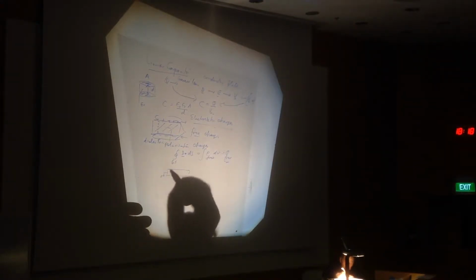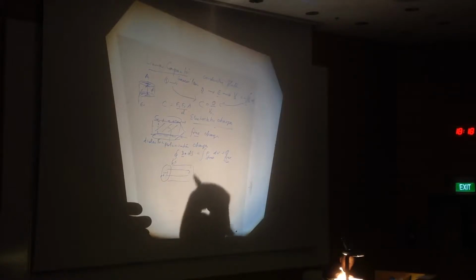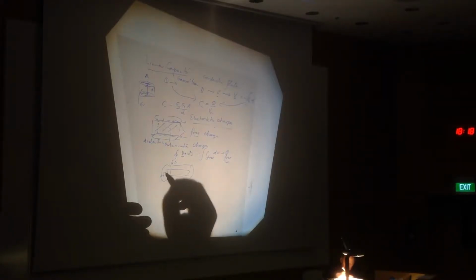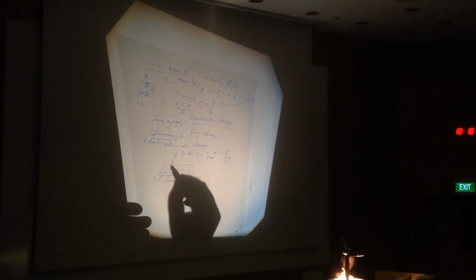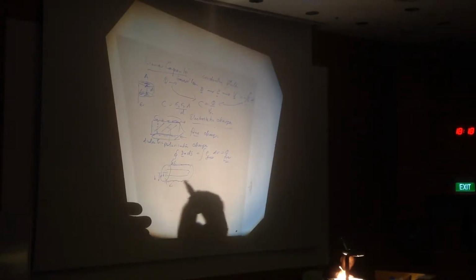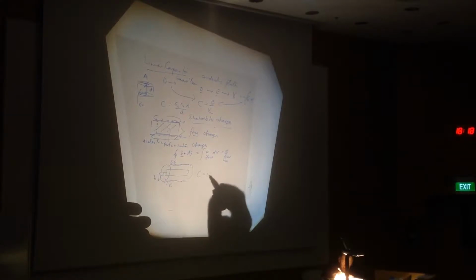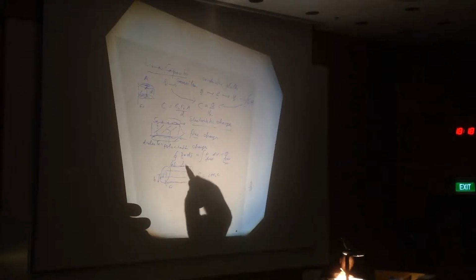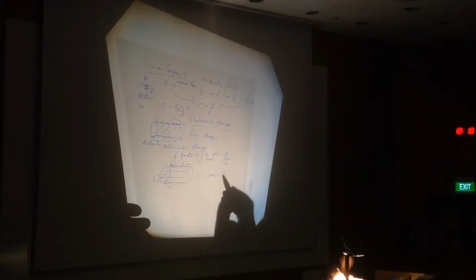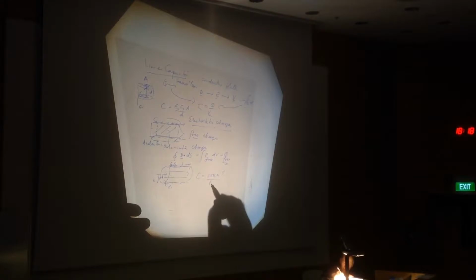This is A, this is B, conductors are here, obviously, with dielectric epsilon R. The capacitance is 2 pi epsilon naught epsilon R times the length L upon ln, the natural log, of B over A. You have to know this result because you have to apply it.